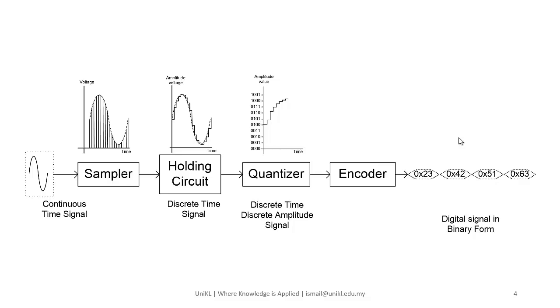That's if we read the signal at discrete time, or at a fixed interval of time. But it can also be done only when necessary, when required, then we read the signal, right? The signal will be fed to the holding circuit sample by sample, which we call sample and hold circuit, then fed to the quantizer, and then formed into the binary signal.